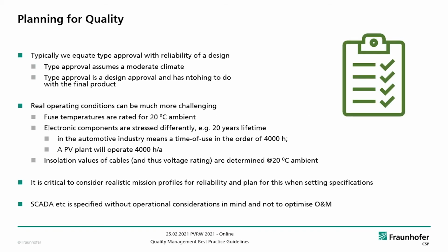So we don't plan properly for quality. We just equate type approval with design reliability. As I said, we don't assume realistic mission profiles, and we assume this is fine. We talk about real operating conditions for simulation of the power, but not what is important for the components. Fuses are very often rated at 20 degrees Celsius. Installation values are rated at 20 degrees Celsius very often, not always, but you can look at them. But people don't do that.